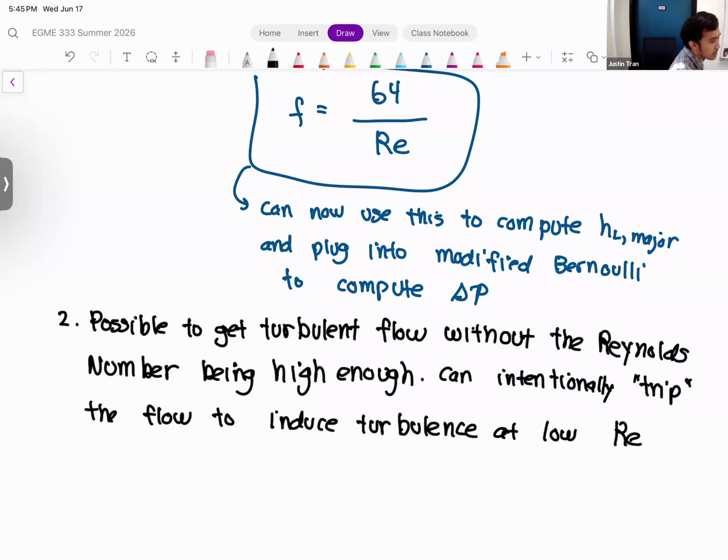Turbulence is chaos, but sometimes chaos is good, because it enhances mixing. If you have a heat transfer situation where you're trying to extract heat from a surface, turbulence will help enhance that heat transfer, and sometimes that's what you want. Say you're designing a fin, or trying to offload heat generated from an engine. Turbulent flow is better in that situation so you can cool faster and push more output from your engine or your computer.